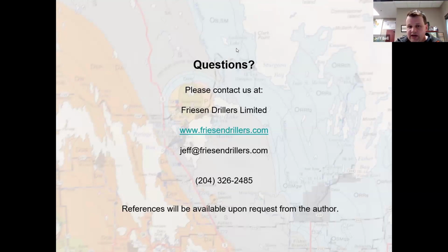We have interconnection of the two aquifers that has been fairly prevalent, mostly, I would say, in the Steinbach area. It's areas where both the limestone and the underlying sandstone aquifers have been commonly drilled for water supplies because they're both fresh. And there was a little bit of an old tale in this area that the sandstone water in Steinbach was quite a bit softer. So it would be very common to actually drill through both formations and allow the two formations to mix, and you ended up getting a softer water quality out of it.